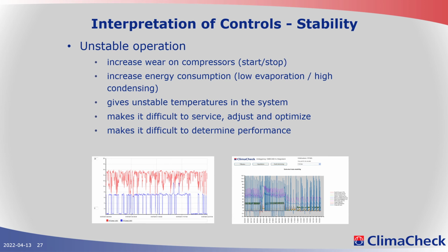Air-cooled chillers, in most cases, have the controls left on some kind of default setting between 35 and 40 degrees condensing, which makes no sense because most of these air-cooled chillers will work well down to, depending on the compressors, well below 30, some 32, but you can get to the minimum allowed condensing pressure for the compressors.